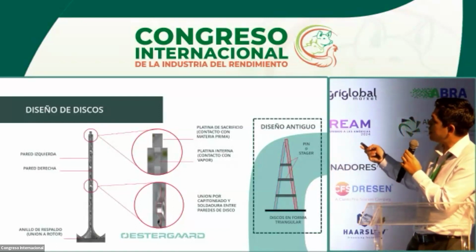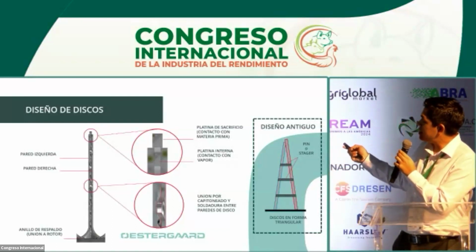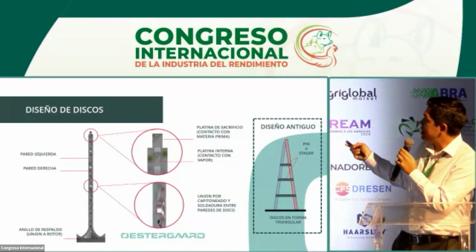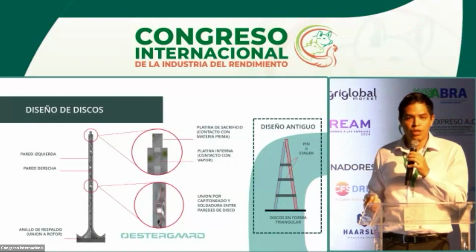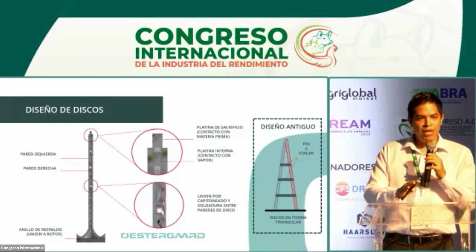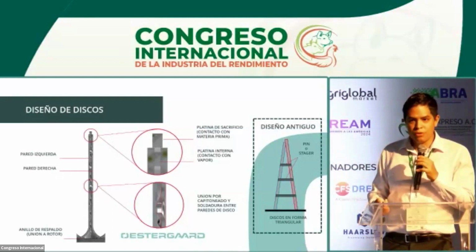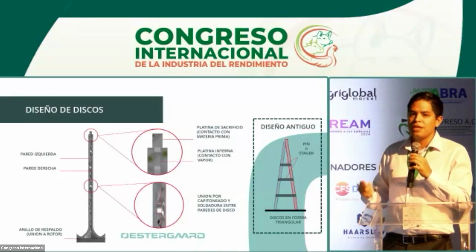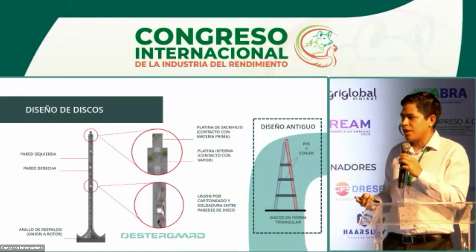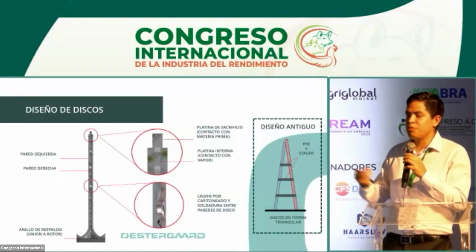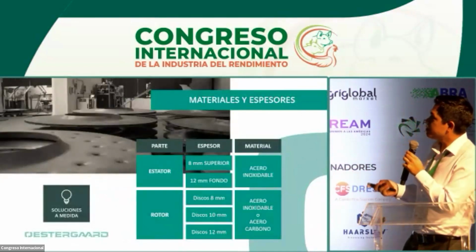In the old designs, we see that the walls overlapped on the end, generating wear and tear of the material, and we would lose one of the ends. Maintenance had to bring new material because we lost the steel. It took a lot of time for this welding, especially since the plates kept over plates were heavier. This will reflect in downtime. It was reflected in increase of current consumption, less capacity for drying. Finally,